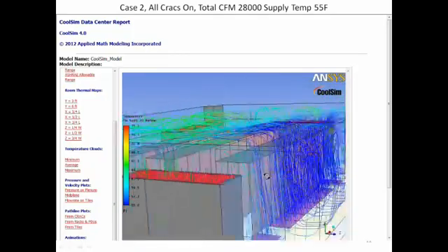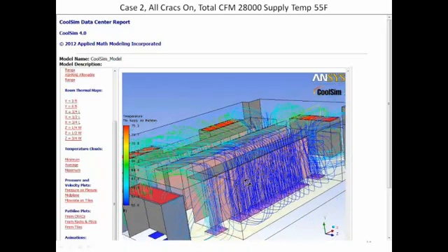Here's the bypass airflow. Now, the bad news here, Liz, is it's hurting us twice. First, we have to pump it with a fan. And number two, the fan's putting a thermal load in the room, and I have to reject it. Right. So not only do I have to put energy into the fan to blow the air to begin with, but then I have to reject that heat caused by the fan in the room through the heat rejection device, and I'm hurting my heat rejection device by making it too cold on the returns.